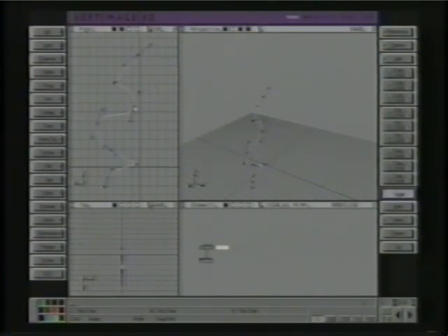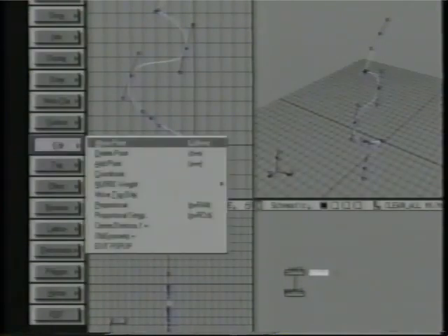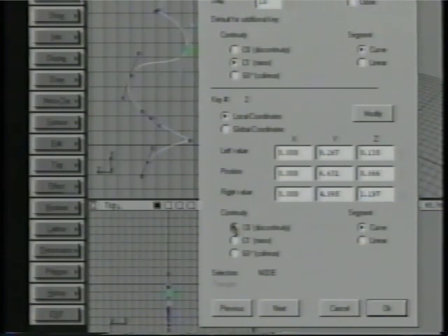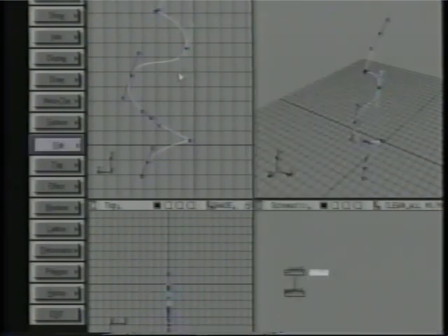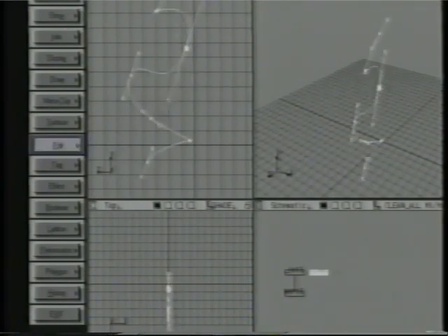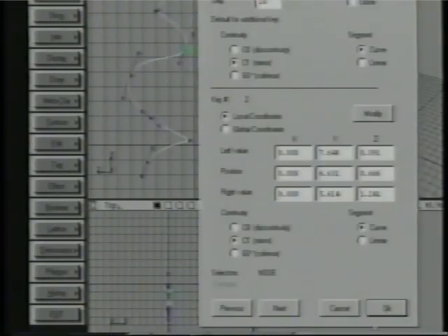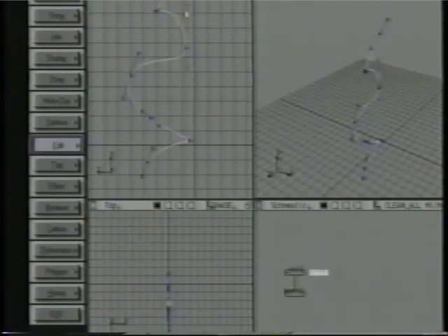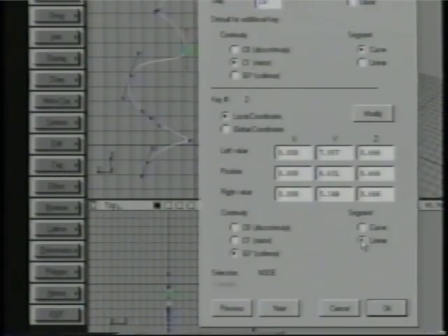If you actually want to edit the node so that it becomes a hard edge instead of smooth, use Edit Coordinate, and then click on one of the nodes. So if you choose Discontinuous, for instance, you'll get a hard edge. And this time you'll be able to edit these handles, and you'll notice they turn light blue. Mirror is the default form, and that's blue. That means as you drag, both sides will have an equal amount of tension. With collinear, those act independently like this, and those handles become purple. Also in Edit Coordinate, you can change a segment so that it's linear instead of curve.